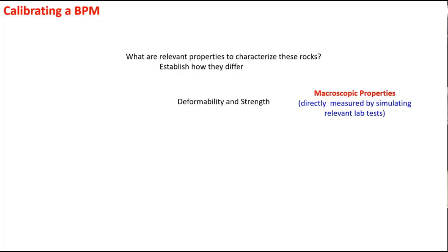In a rock, like in a UCS test for a granite, it's going to go up and it's going to drop down very quickly. We say that's the strength, right? If we load the rock differently, it's going to have different strength. If we put it in a triaxial cell and we squeeze it and measure the force at which it starts dropping down, it's going to get bigger and bigger the more it's confined. So that would be strength, right?